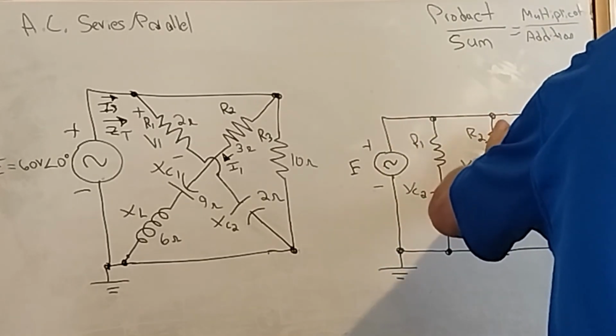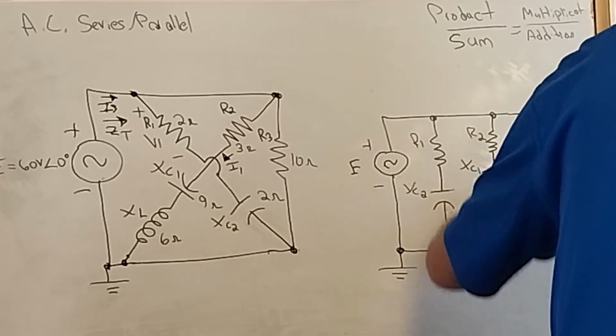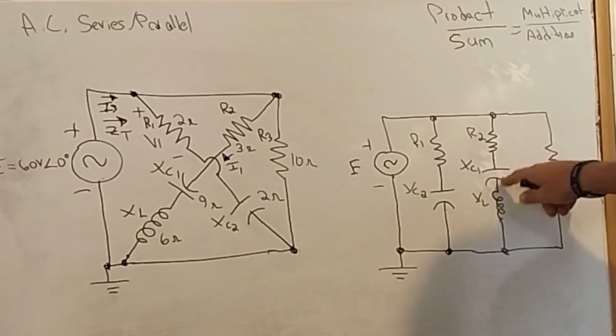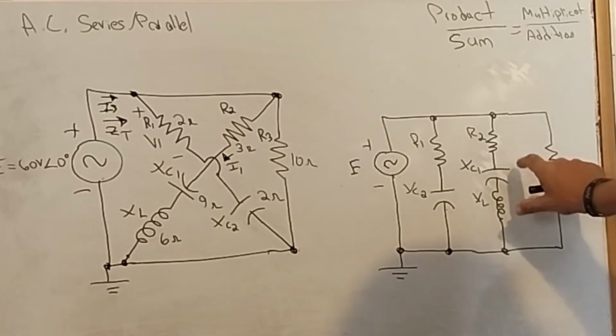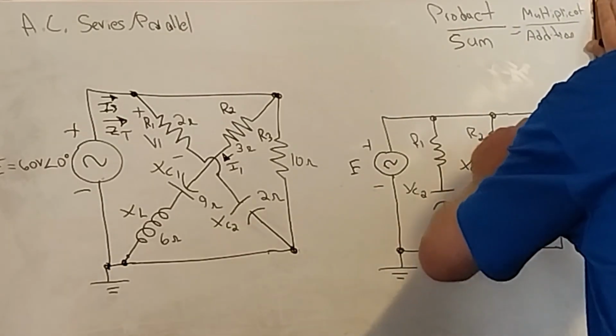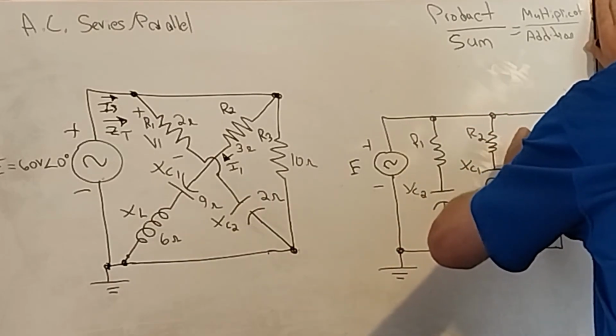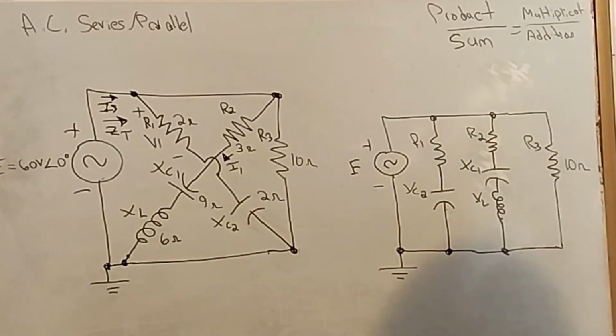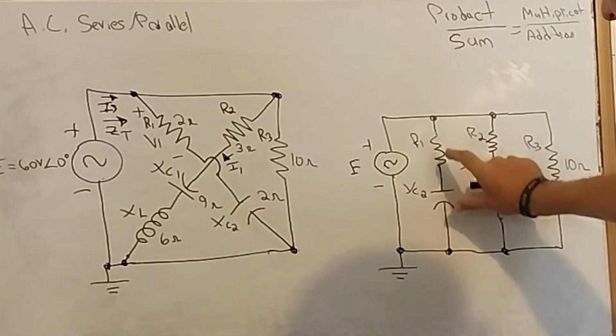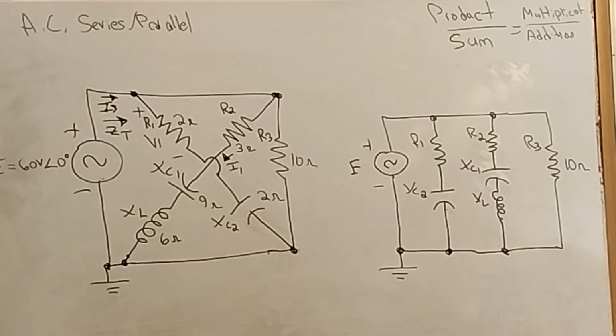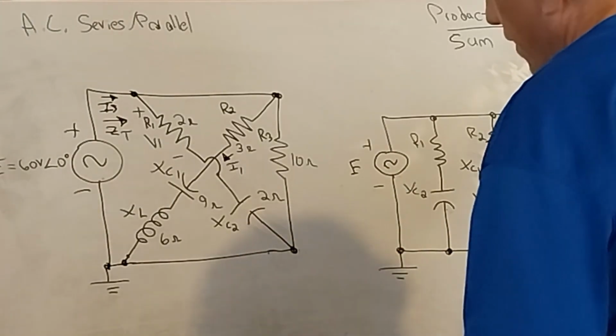And you could write them the other way. I could have left this other resistor in this strand and put this strand, or this column over here, but I don't need to. They're still going to be done the same way, because if you look, they're all in parallel. But I still have to do these series combinations first. And it's probably good if I write the values here.